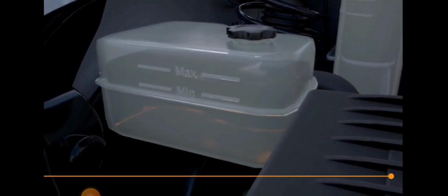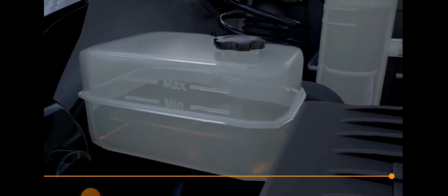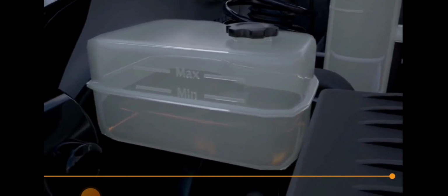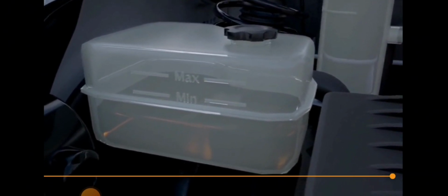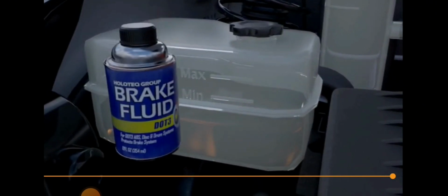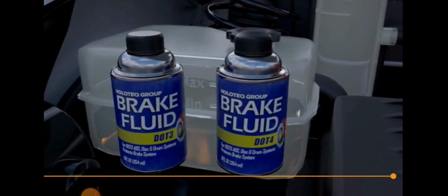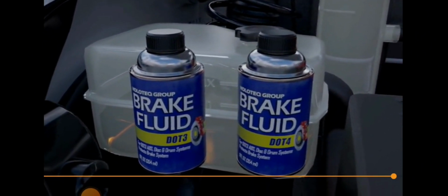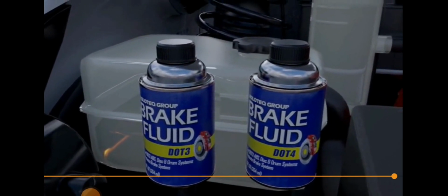When brake fluid level decreases below the minimum level, fluid must be increased and the system checked at maintenance workshop. But before increasing the fluid, check fluid specification on fluid reservoir lid, where there are two known types of specifications, DOT 3 and DOT 4, noting that the increase of fluid with different specifications will harm the system and lead to damage of rubber parts and cause fault of brakes.